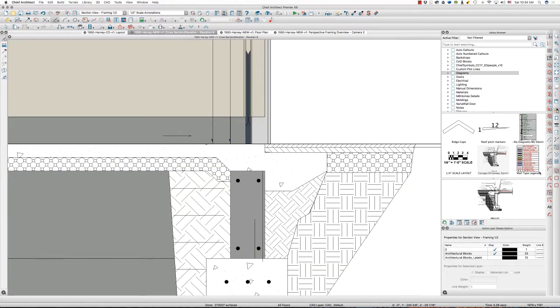All right, a few things are not visible right now. I'm going to go into my Select Contained Objects option. I'm going to select this steel and this steel and do the View Draw Order, and just click once to the front, bring forward. Very good. And then I'm going to drag across here, and look, I've got some items hidden, some polylines and some circles hidden, and we're going to do the same thing, draw order, bring to the front, and there it's visible.